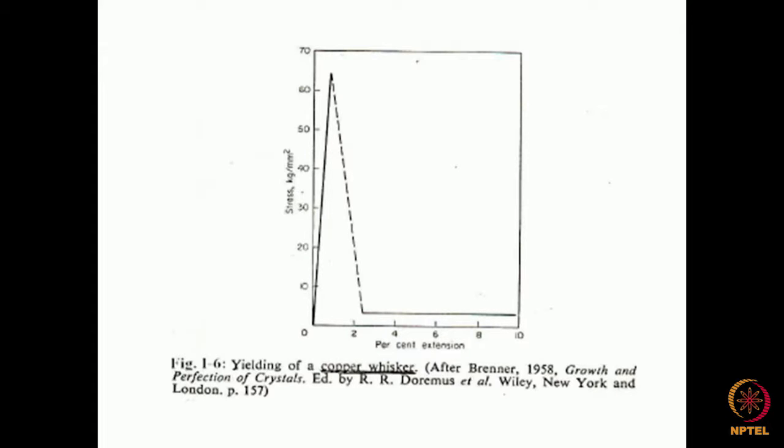Okay? If you take that material, point defects in bulk material will be more than in nanomaterial. Yeah, that we can calculate differently. Essentially, point defects are inherently present, if the dimensions are sufficiently large, because the point defects lower the free energy.